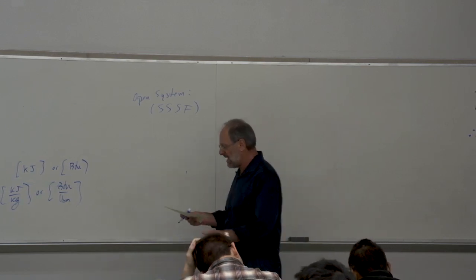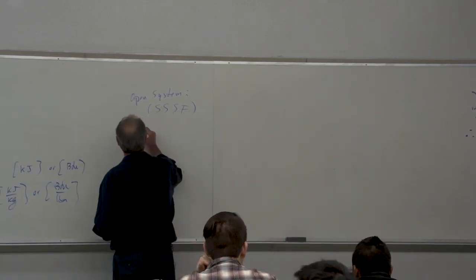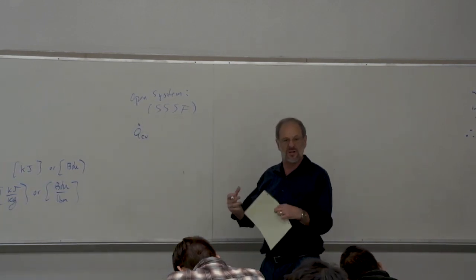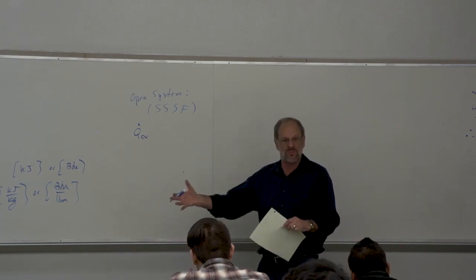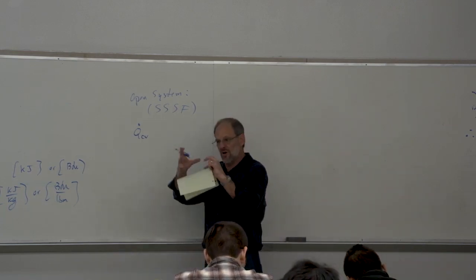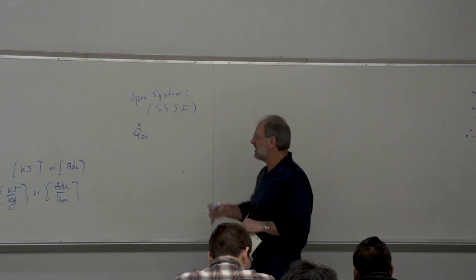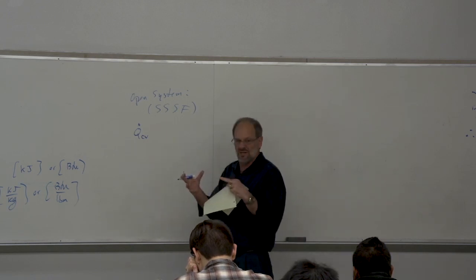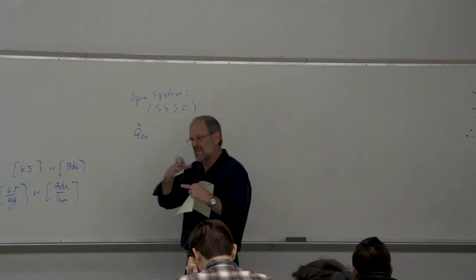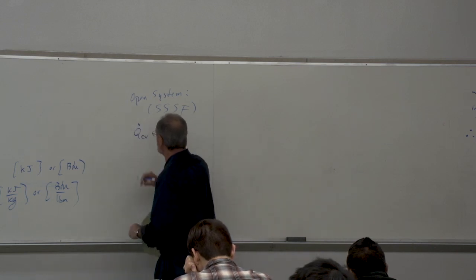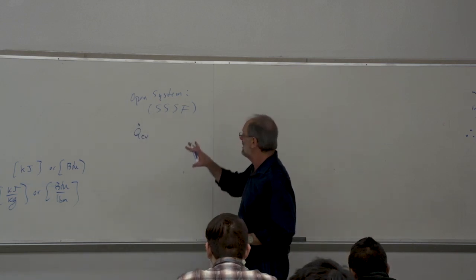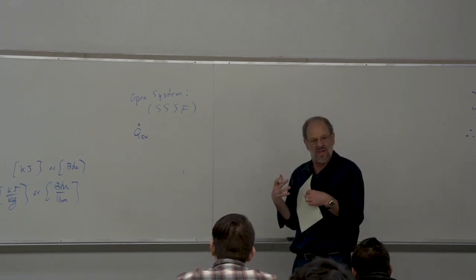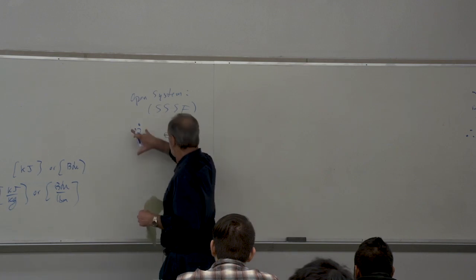So for these processes, the equation is a little bit different. We have Q dot, and usually we put CV just as a representation of the control volume, just to remind us we're talking about an open system. In other words, there's going to be flow into a fixed volume, which is our control volume. So the volume within the pump will be the control volume. The volume within the turbine is a control volume. The volume within the compressor, that's the control volume that we're dealing with. And this represents the rate of heat input. Now, please note that they're open systems. They're processes that involve flow. So we should have everything on a rate basis. Right? The rate of heat transfer.